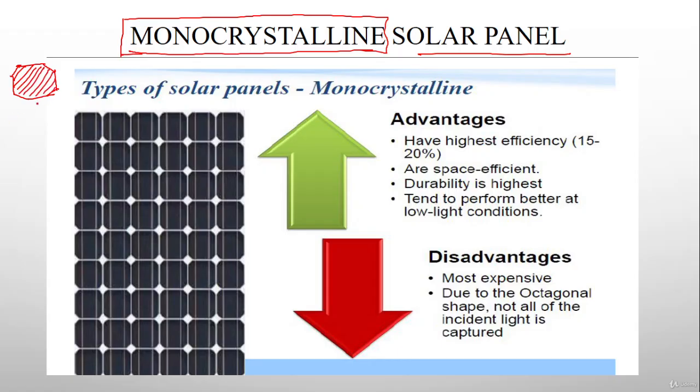And that is why it is called monocrystalline. Mono means one, all one silicon structure we are using over here. Actually, we are not diffusing different kinds of crystals to form one solar cell. It is only one pure form of silicon with a boron-doped material that we are using to create the wafers of these solar cells. So that is why, with this manufacturing technology we use for preparing this solar cell, such panels are called monocrystalline type solar cells.